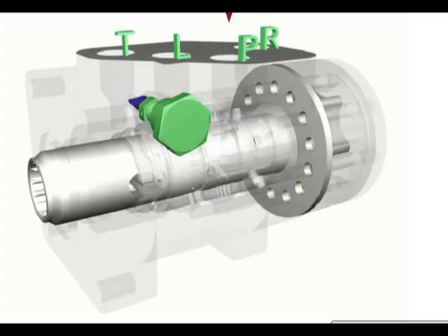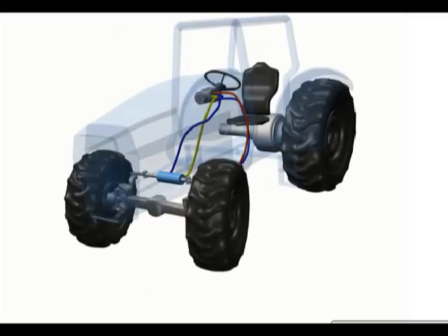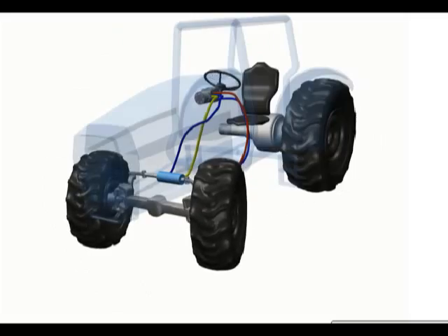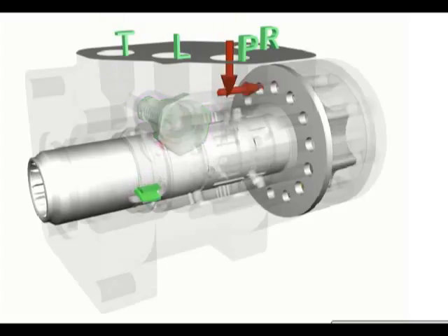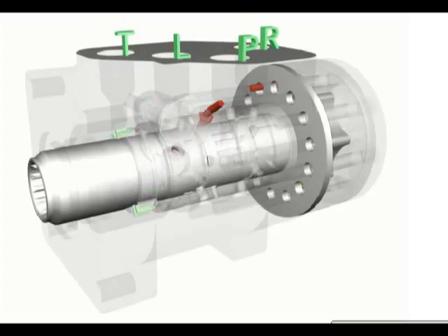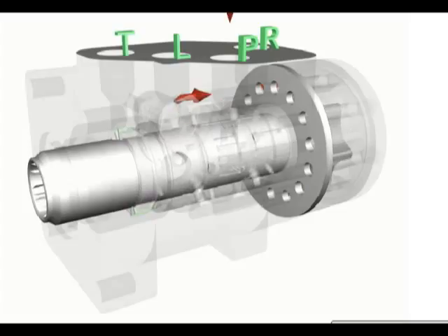The relief valve is passed through the P port to the T port of the unit and flows to the reservoir. Fluid flow is routed to the steering cylinder and turns the wheels to the left. Rotation of the steering wheel clockwise reverses the flow path through the unit.